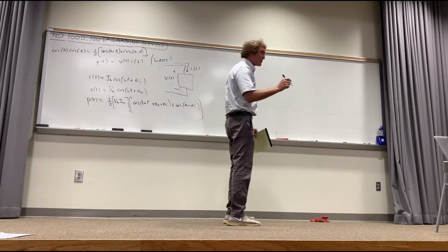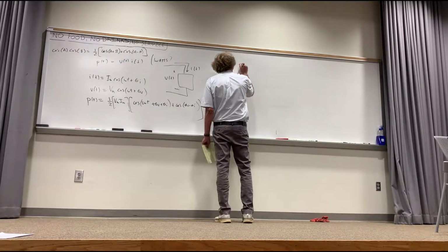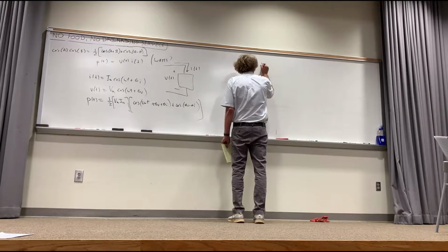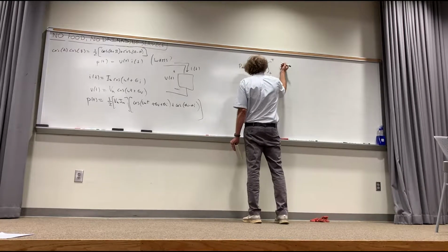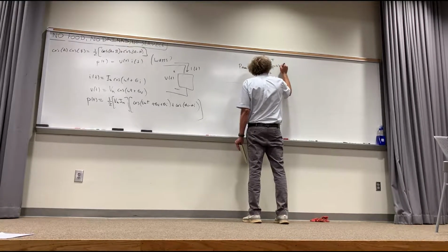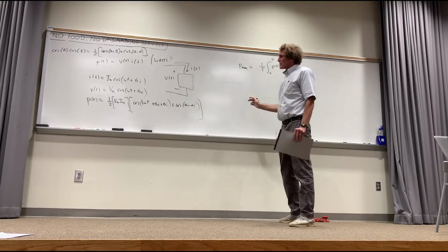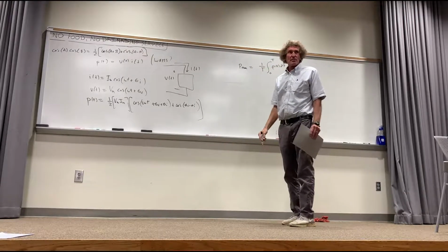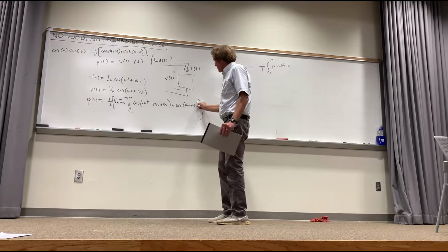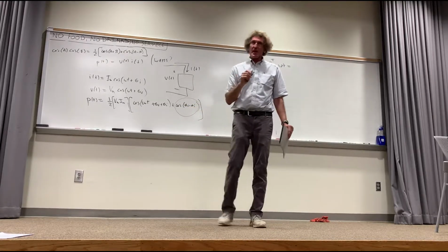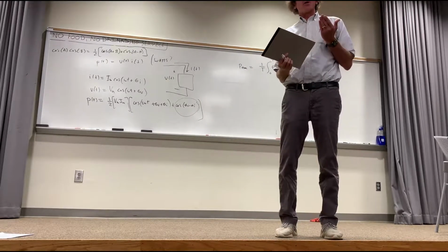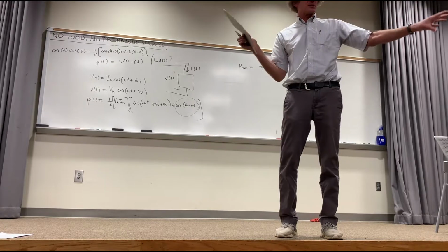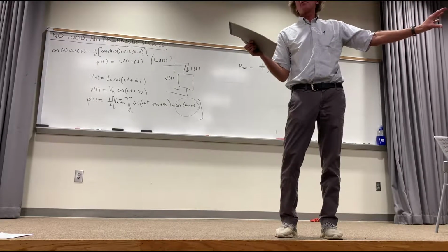Now, after that, we took the average power, and we said P av, the average power, was equal to 1 over T, where T is going to be the period, the integration from 0 to T of P of t dt. Instead of rewriting that whole thing, I'm just going to talk my way through it. This term right here is a constant. Theta v minus theta i, the angular difference between voltage and current, is a constant. Follow me? If the load doesn't change.